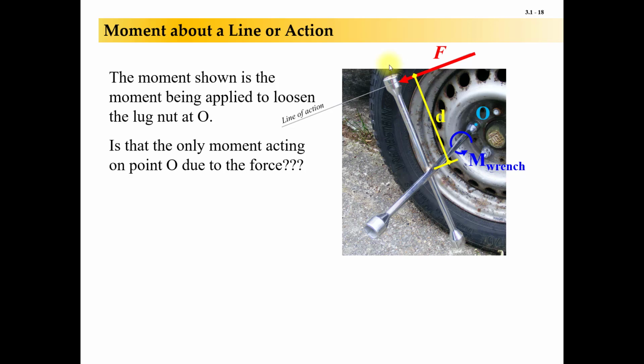which is this perpendicular distance here from this shaft out to this force. This force is acting along this line of action. And that's great. That is the moment that's going to cause that lug nut to want to loosen.